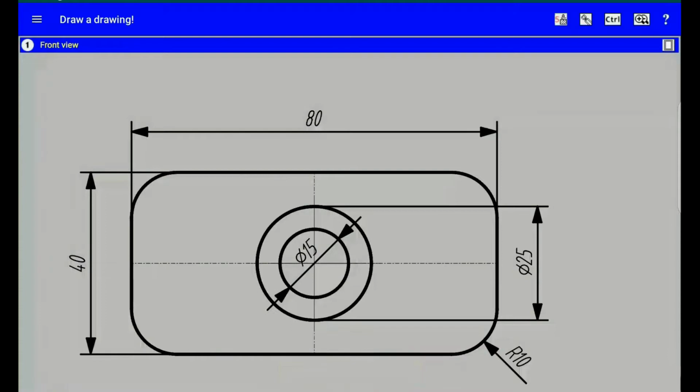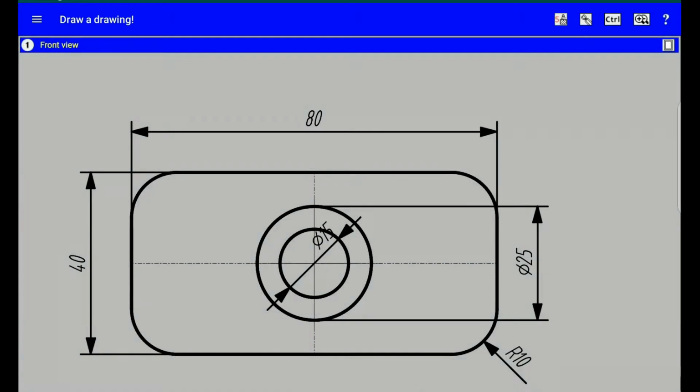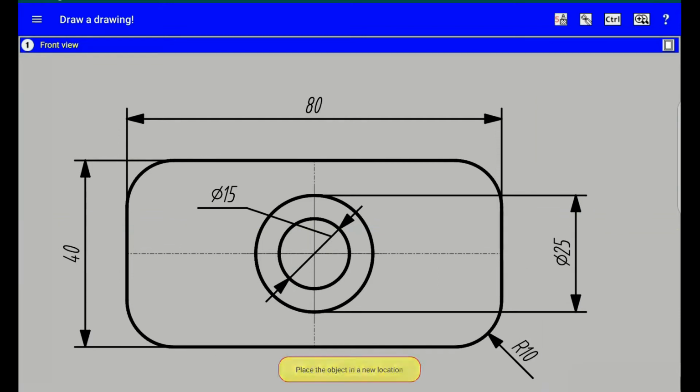At the diameter, we first move the designation of its value away from the middle. And then we will generally tear it off the dimension line. We did this so that the extension line did not go out from the center point, through which many lines pass. Let's also correct the dimension, to which the line of symmetry comes close.